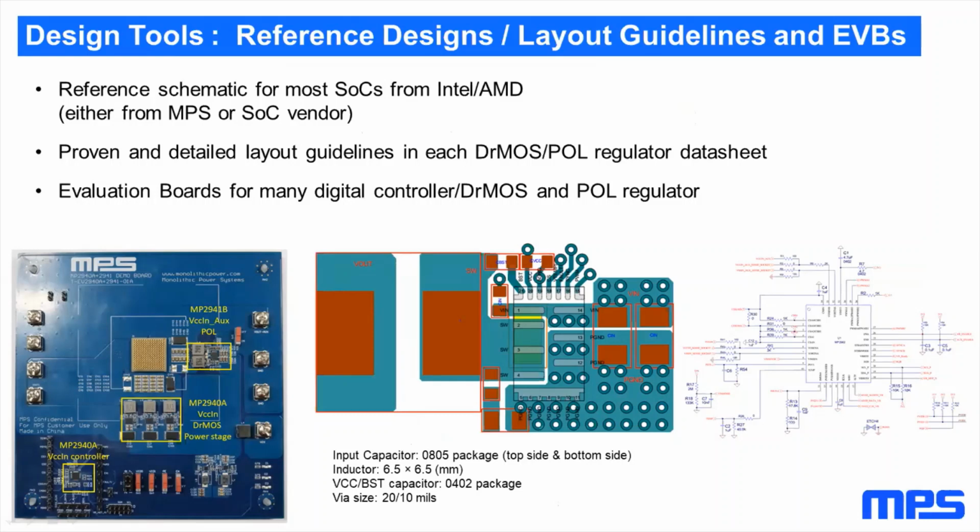Every IntelliPhase datasheet has detailed layout guidelines, and we provide additional presentations for the controller layout. If possible, you should strictly follow the layout guidelines; especially the placement and routing of the power stage input capacitors are quite important. If you are not sure, we will review your schematic and your layout. We can do this simply by email, or we can also set up Zoom or other meetings to do the layout review online. Finally, we offer several evaluation boards where you can use the test tool from the corresponding SoC vendor. One example would be the Intel VRT tool to do the load transients and all these validation steps.